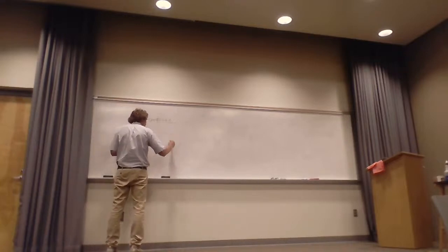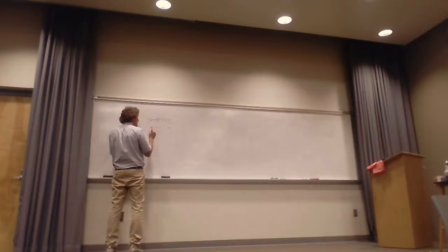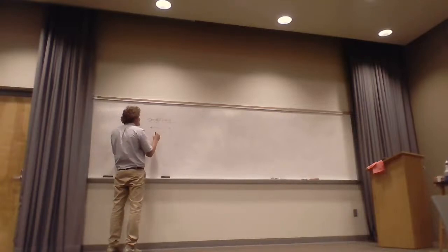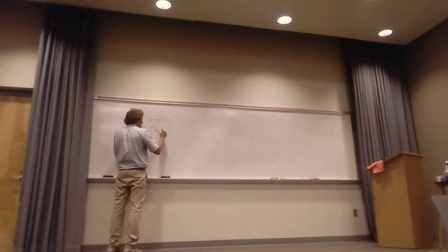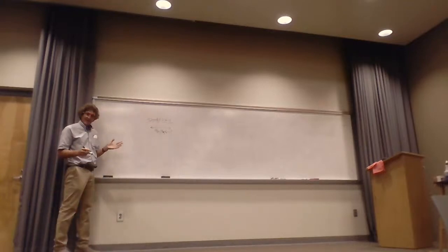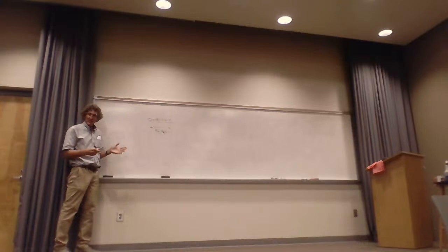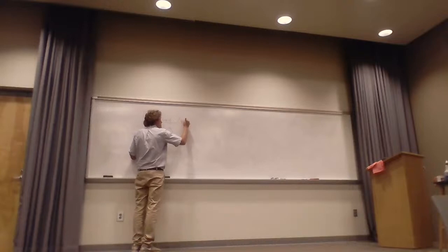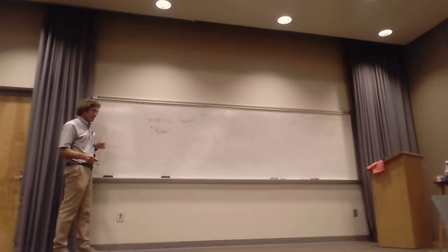I'm going to have some thick piece of metal. I'm calling it thick. A millimeter, that's not thick, but it's thick for what I'm talking about. And this is going to be a shield thickness. And it has some conductivity, which I'll call sigma SH, and some permeability, mu relative. Almost always epsilon relative is 1, but it can change. Anyway, the shield has a large conductivity. It's going to be a good conductor. Y'all follow? So you can assume for shielding that the sigma of the shield is much, much greater than omega epsilon. Just don't worry about epsilon omega.